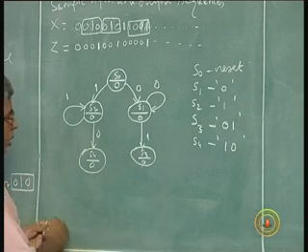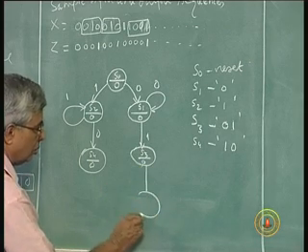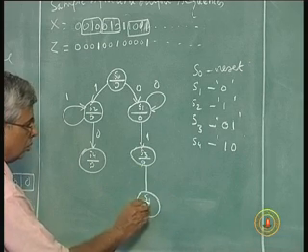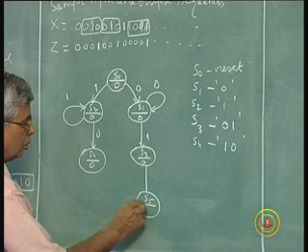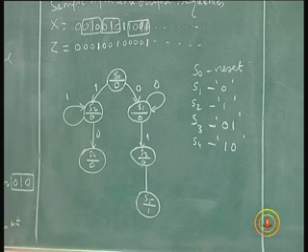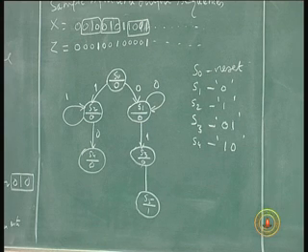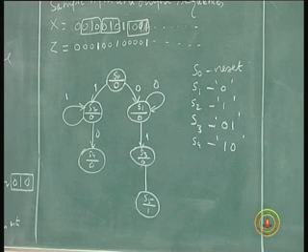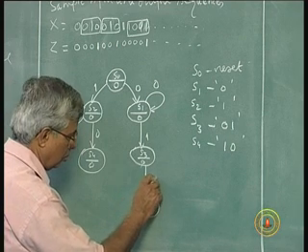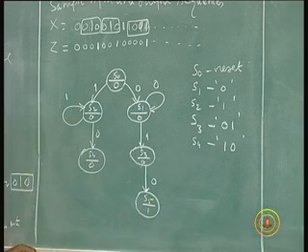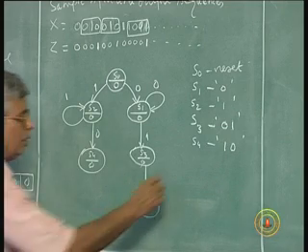I cannot go into any other state because, S5, the output has to be 1 here. For a new state in which the output has to be 1, I cannot go to one of the states that is already there, because all those states are only zeros. So this is a 0 0 state, that is S5.